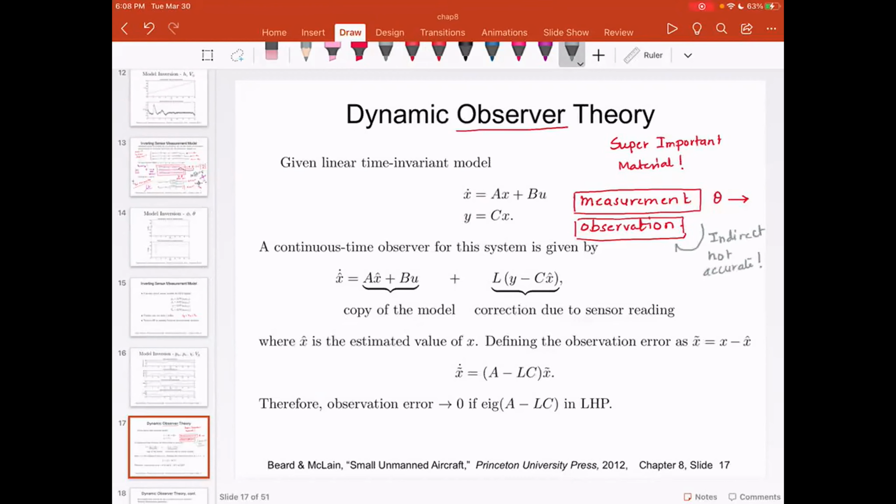So with observation, you are trying to get an assessment, or you are trying to see what the measurement is, but you are never going to get an actual measurement. You will have either noise, so the measurement would be fluctuating, or you would have drift, which means even though ideally the measurement is constant at, say, 30 degrees, you will notice that your scale is drifting slowly. So the idea is we don't have a direct way to get this true value.